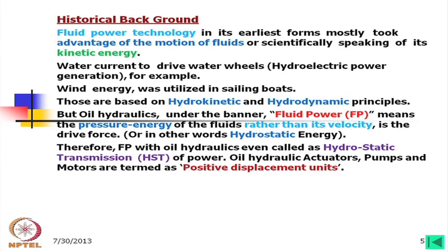Therefore, fluid power with oil hydraulics is even called hydrostatic transmission of power. In short form we call it an HST system. Oil hydraulic actuators, pumps and motors are termed positive displacement units.